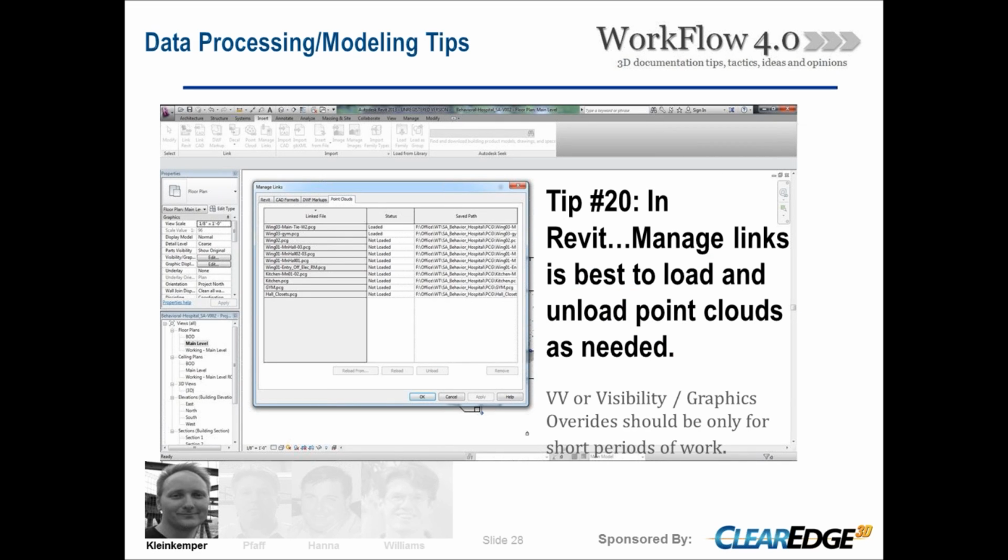In Revit, we found with working with gigantic scan files that it is best to, under Insert, use the managed links and load and unload as needed. You end up using that a lot. VV is okay for short overrides to quickly hide or turn off for just a couple commands and then turn the scan back on. But you will greatly improve your performance if you use managed links and actually unload the files altogether so that the computer's not thinking about them.